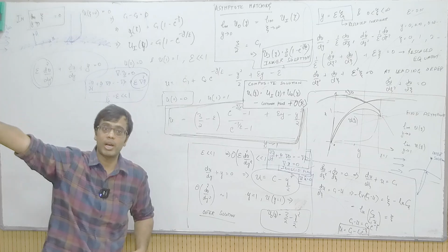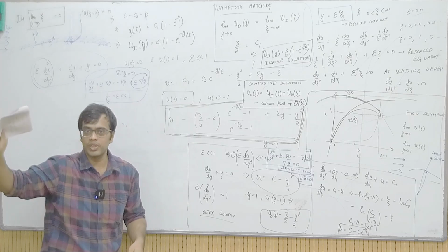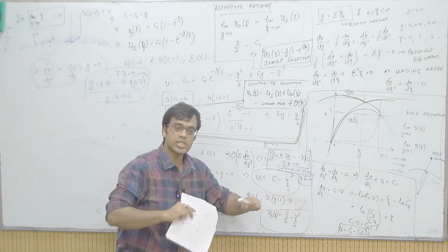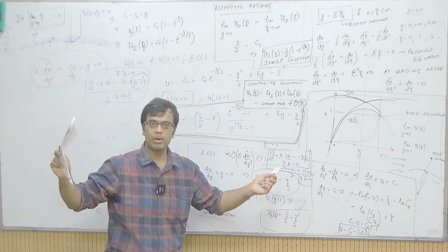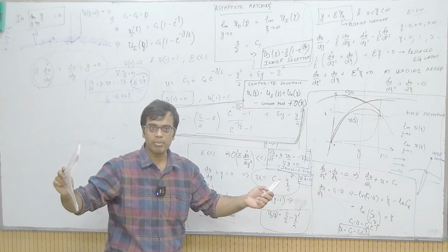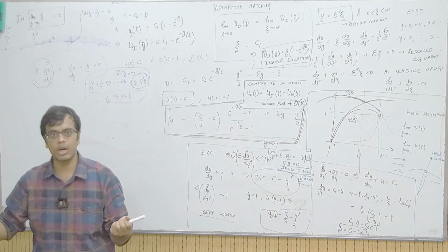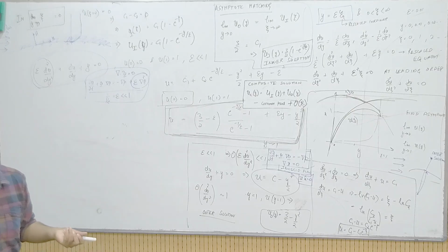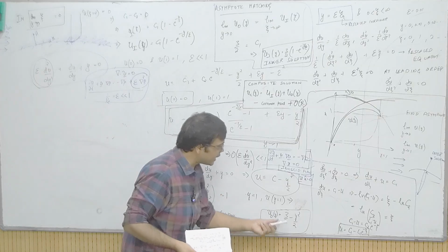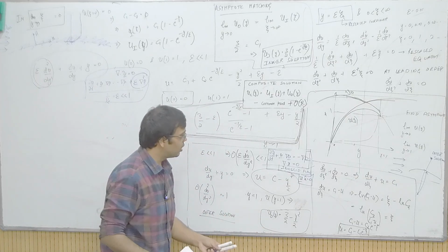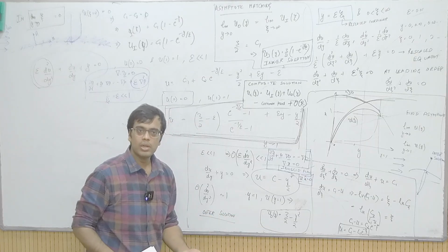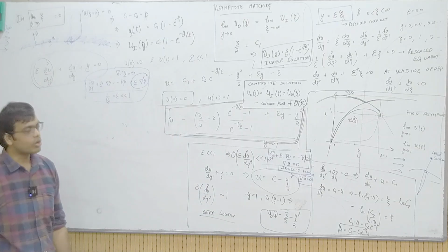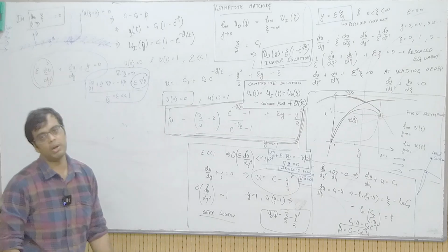Forget about Stokes flow past a sphere or something where we talked about outer field and inner field, but we just solved for the full flows over the whole domain. Okay, because the governing equations that turned out were linear for the flow everywhere. So we just ended up solving those equations. We need that boundary layer concept in high Reynolds number flows to be able to match this no slip boundary condition, because the outer limit cannot match the no slip boundary condition.